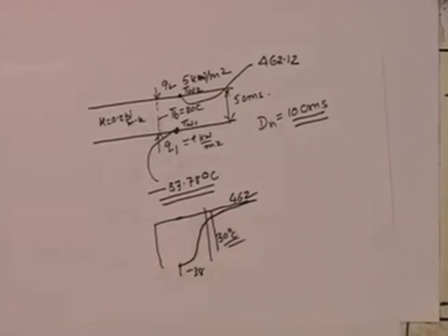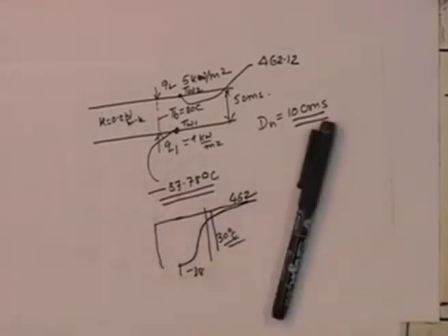It is for this reason that we are usually interested in finding out the solutions, because no wall should become too hot or too cold, because it might affect other processes on the outside or inside of the annulus. In as much as the bulk temperature is only 30 degrees centigrade, the wall temperatures can be enormously different for just very small heat fluxes of 1 kilowatt to 5 kilowatt per meter square. It is for this reason that we take particular care in evaluating our Nusselt numbers accurately in annulus flows.